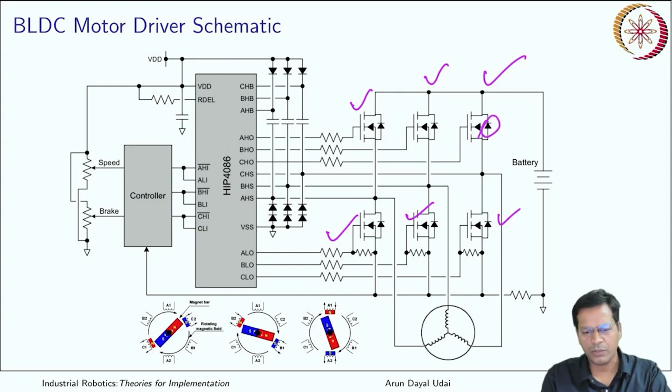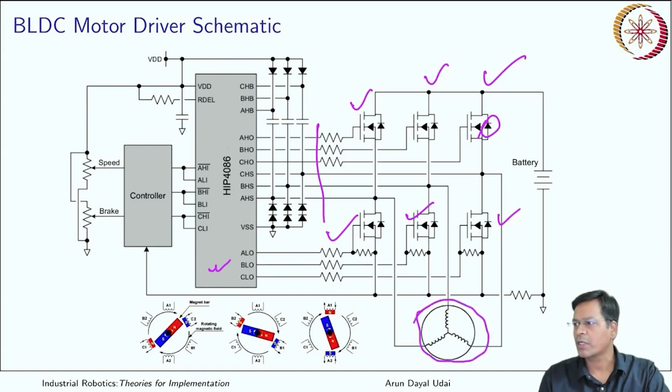All these are connected by the 6 wires which are coming from the controller which is here. So they can easily control the 3-phase current which goes to the winding of these coils. That is what is creating the rotating magnetic field, and finally your rotor is following the rotating magnetic field.